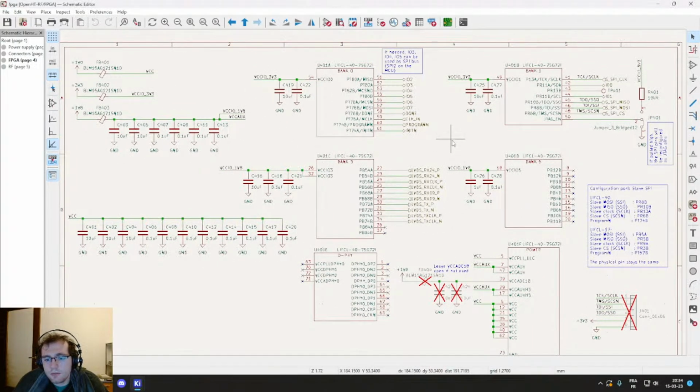FPGAs come in two main form factors nowadays, BGA and QFN, and BGA can be a pain to design but also to play with. It might also heavily increase the cost of the board if you want to manufacture a BGA-routed FPGA, because if you have a fine pitch device, the manufacturing processes become expensive very, very quickly.